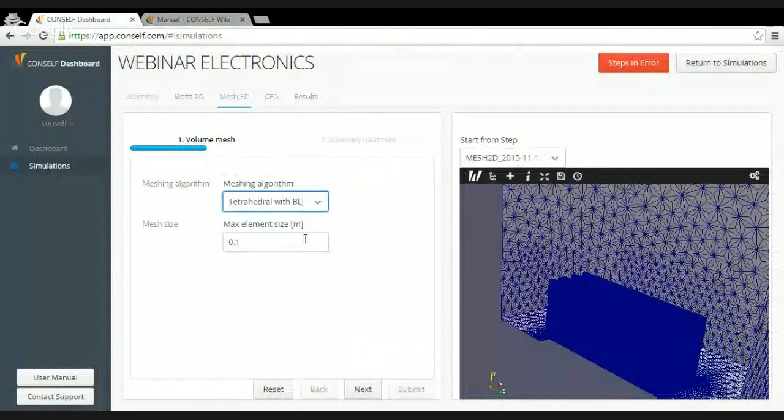For the purpose of this simulation, let's stay focused on the tetrahedral mesh, and let's use a resolution this time for the volume elements inside of the domain of 5 centimeters. This resolution is similar to the maximum surface size we applied earlier.